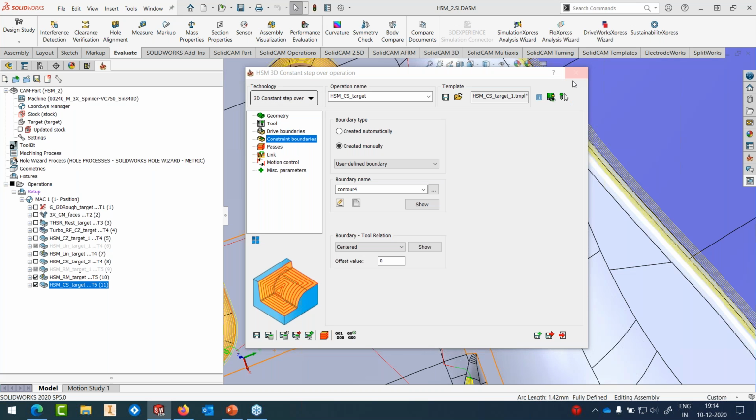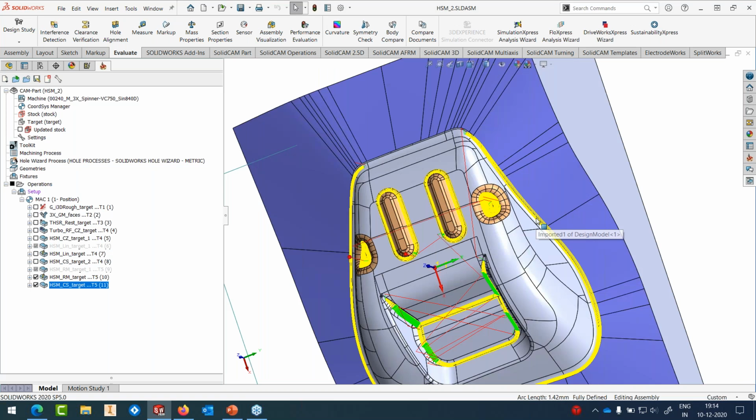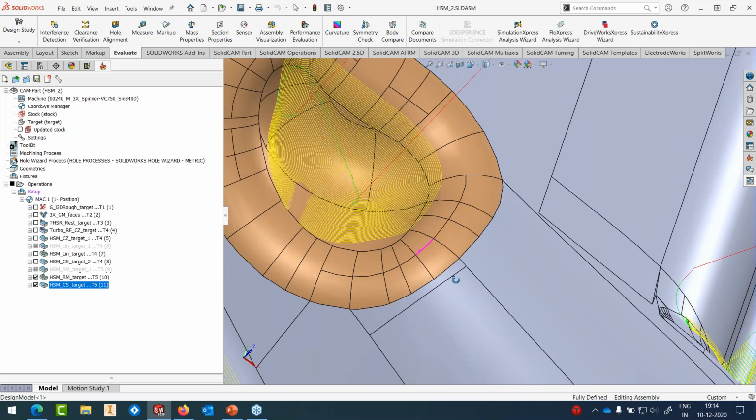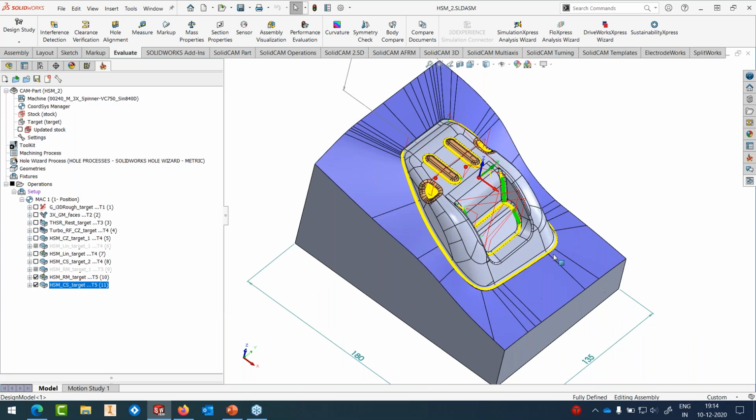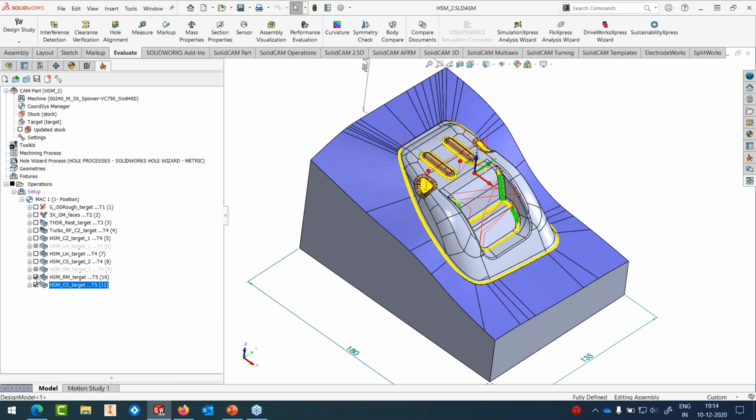We can run the simulation. We can do a lot of other things. This calculation is done. We're machining, and this entire part has now been calculated using different techniques. What you've seen here was the technique of constant Z machining, linear machining, and to some extent constant step over. Although we had several other machining techniques, none of them were really useful on these kind of paths. Okay, they have their own specific use, but most of the time this is the one that you're going to